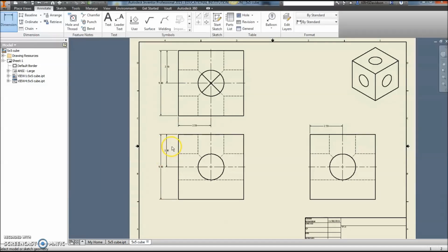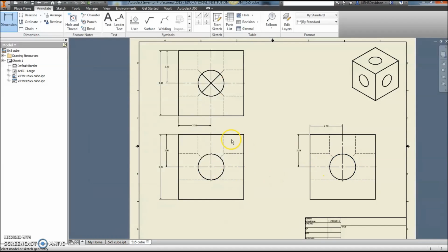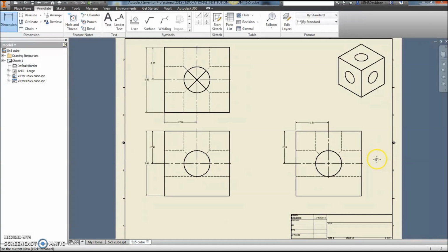And even though it's over here already, we'll go ahead and put one here and here, because this is specific to this hole, so we're not over dimensioning it at all. We don't need to put an overall because they're covered there and there. We've got a height and we've got a width, so that's already there. So we're good. Yeah, we should be good there, like that.